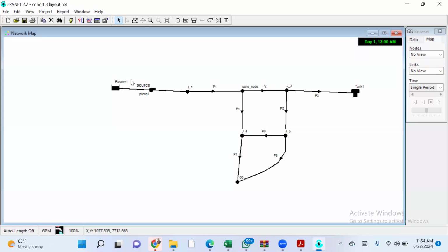For a typical water design in a residential area, there are about 2 patterns or 4 patterns in a day. Between 12 in the midnight and 6 a.m., everybody is sleeping. The water consumption has a pattern. Between 6 in the morning and 12 in the afternoon, there's a pattern. Between 12 in the afternoon to 6 in the evening, people have gone to work. There's a pattern. From 6 in the evening to 12, there's a pattern. Now, these patterns are defined by what we call peak periods.